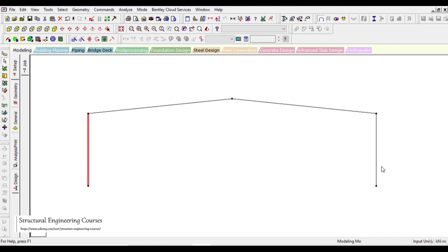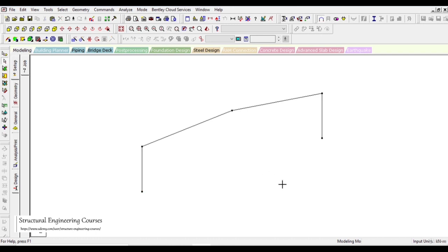But nowadays, with the invention of new software and the introduction of various high-level analysis software, we can simply model the full pre-engineered building shed or warehouse, so that we can check and analyze and design the forces and bending moments along both the axes, that is along X as well as along Z. My preference is also that we should always go for the three-dimensional analysis of the PEB shed, as there is no purpose of doing the 2D analysis when you have such advanced software.